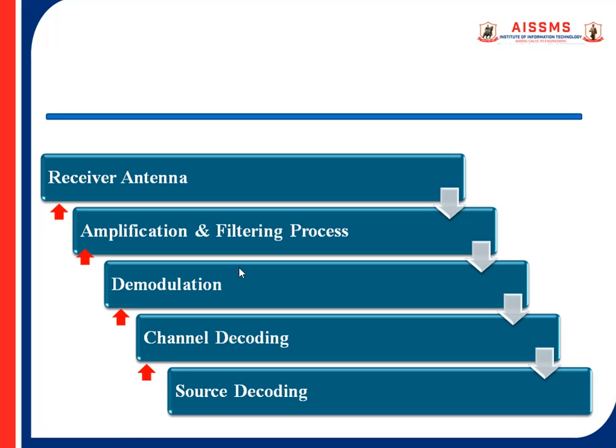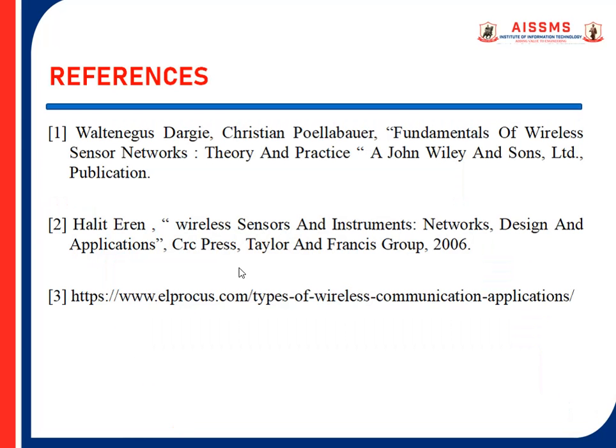Finally, the baseband signal undergoes a pulse shaping process and two additional stages of decoding, channel and source, in order to extract the sequence of symbols that represent the original analog signal, which is the message.